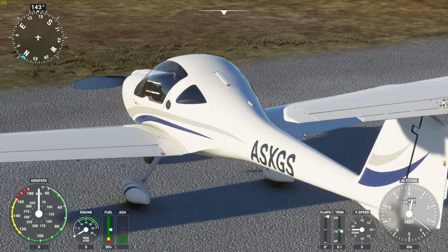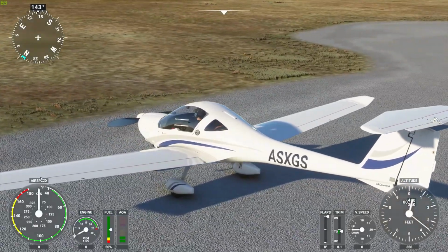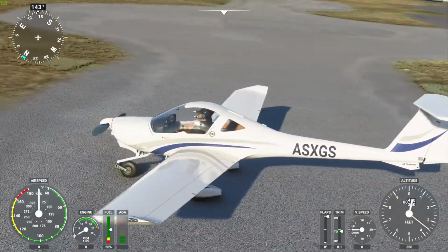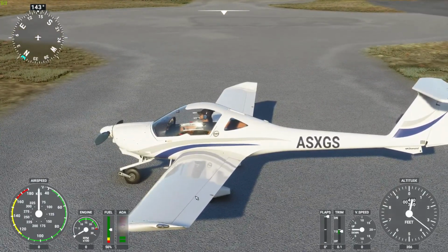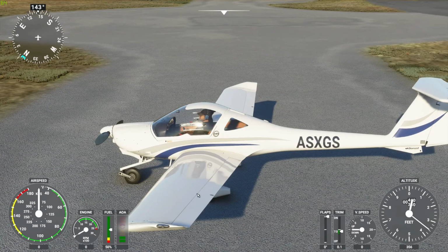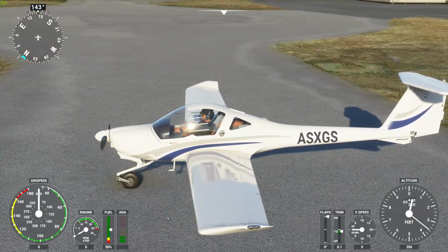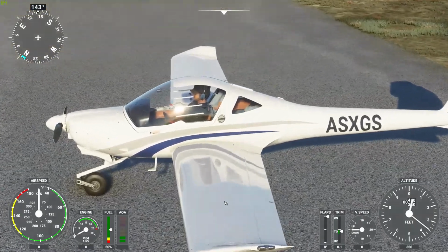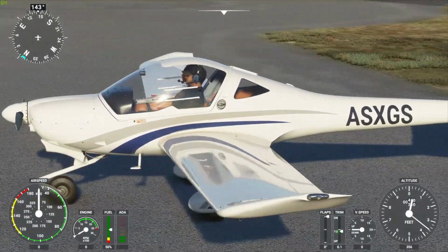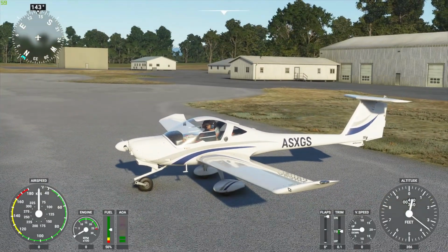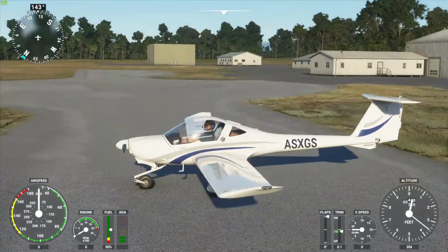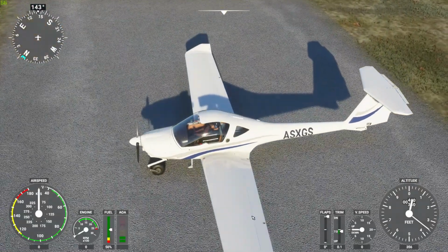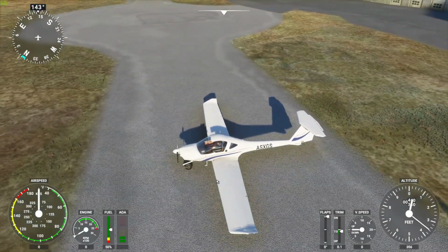So that's the elevator. So another thing that we can take a look at is it's a very smooth wing. There's no vortex generators, so these are little tiny, basically little blades that you might see a line of. They have them on the Cessnas out towards the wingtips, and particularly in front of the ailerons. So this is really a laminar wing, so it has a very smooth airfoil section, which is also common on gliders and aircraft with quite a high aspect ratio. So the aspect ratio is basically how wide is it compared to how long is it, or I should say actually how wide are the wings compared to how skinny they are. So we can see that it's quite a long wingspan, and they're quite skinny.